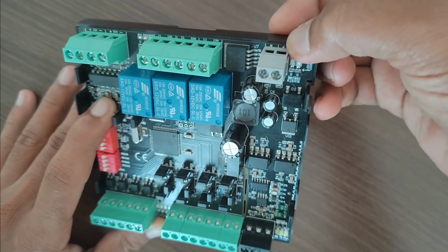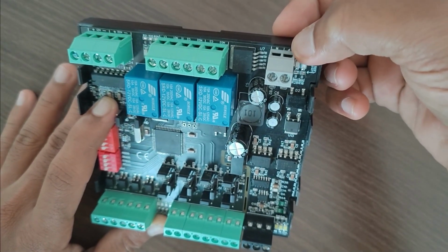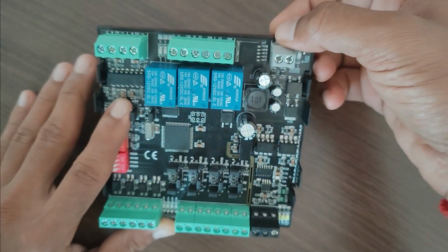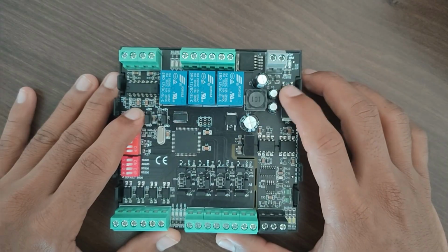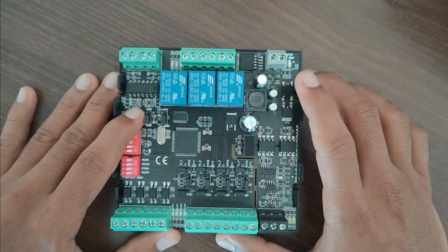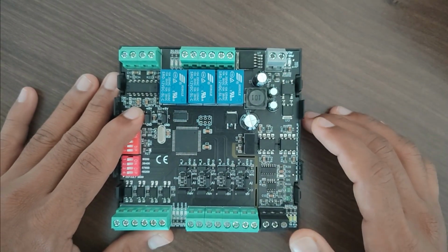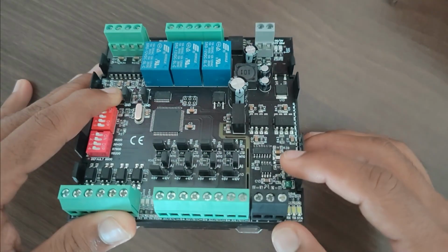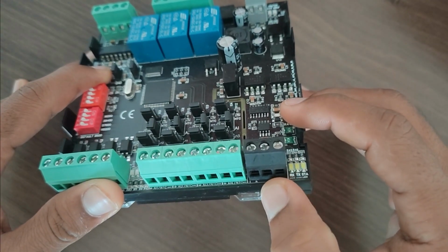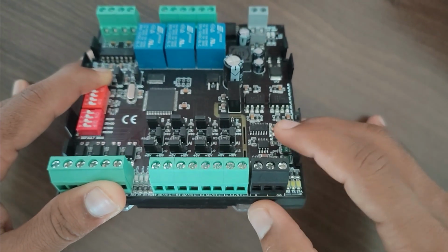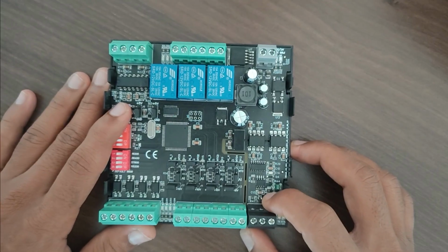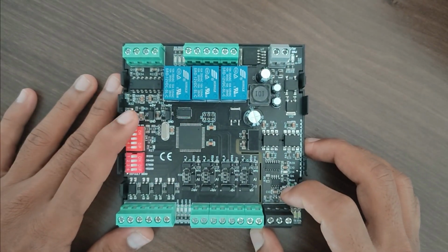In this power supply, we have provided the configuration as positive and negative, where you can provide up to 24 volt DC in any direction. Here we used the bridge rectifier, which supports the board for the reverse connection also. In this RS485 communication, here we have the configuration as A and B, A for the positive, B for the negative. You can connect the RS485 cable with the PC to get the data.